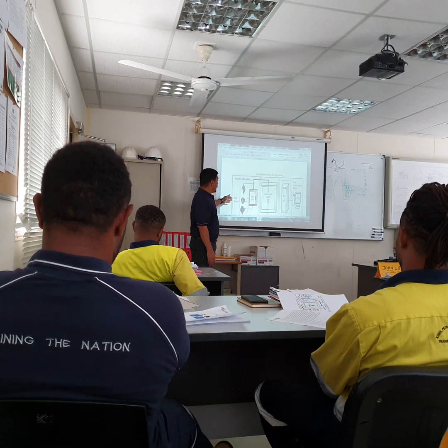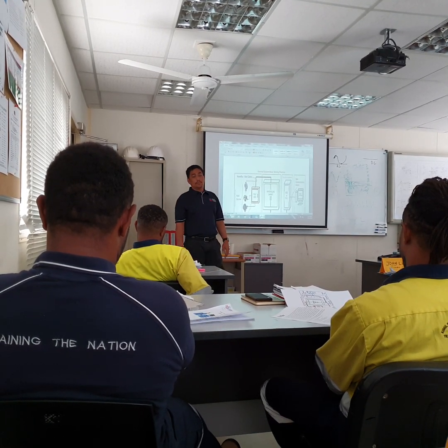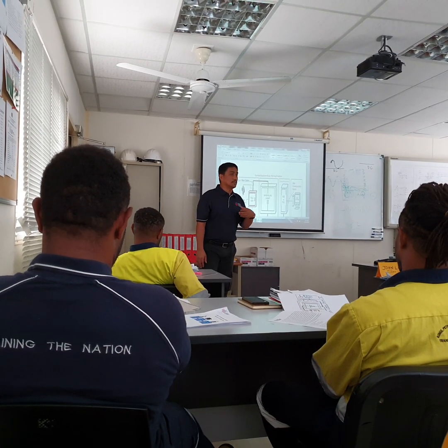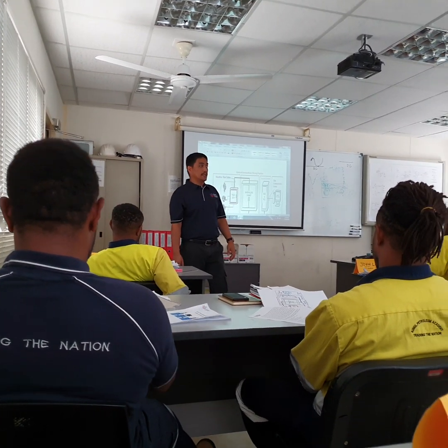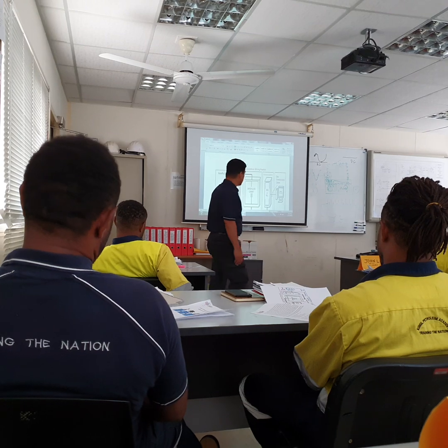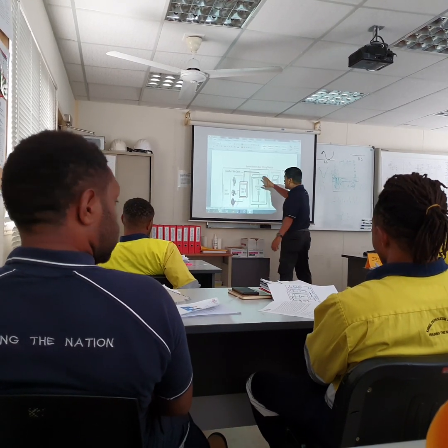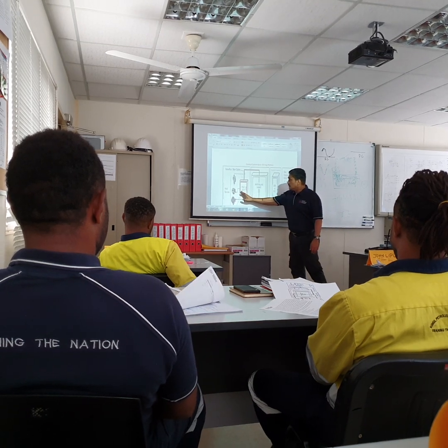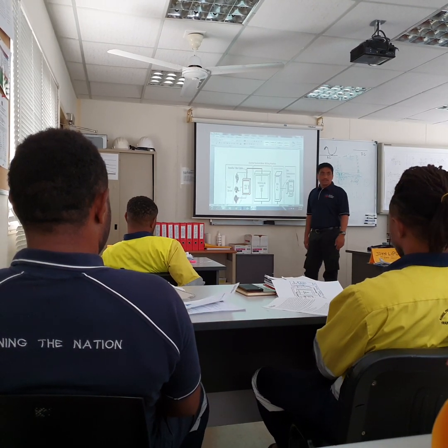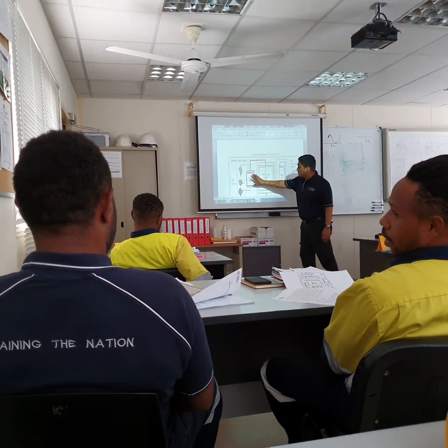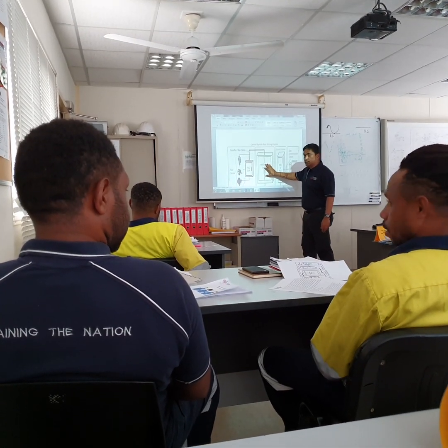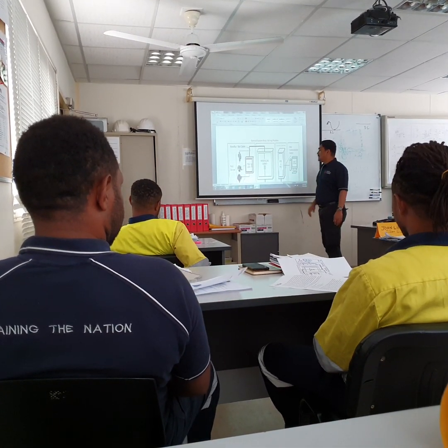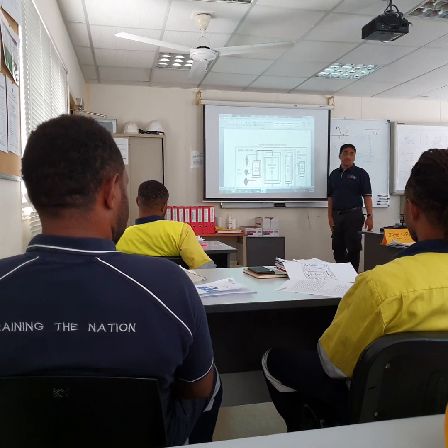And those are your field devices. For example, it measures pressure, it measures temperature, and so on. But the marshalling cabinet, these are the connections between the DCS and the field box. You will find lots of cables here, and the DCS is connected to those cables.